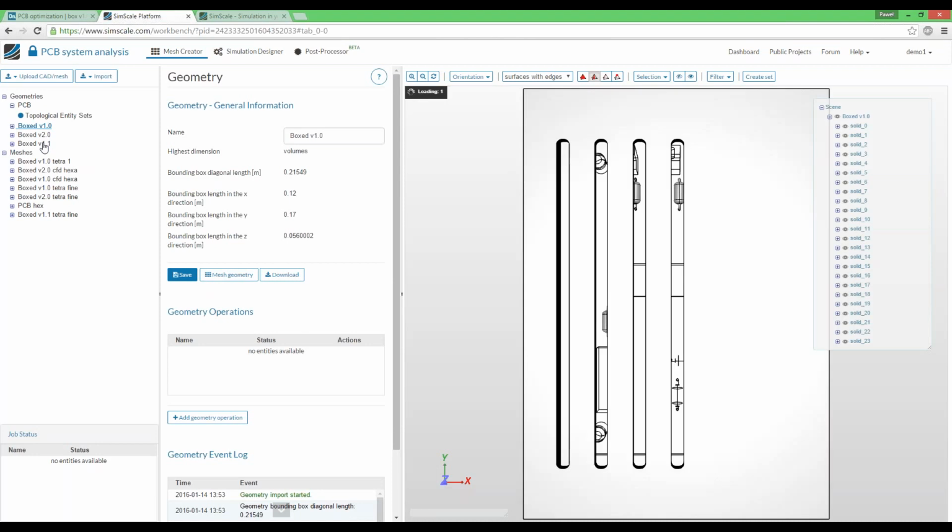There is a question, is the mid-surface meshing available? You mean a surface that is within the geometry itself? In general, you should provide a geometry or a solid element that is whole within itself. If you have surfaces inside, they will be considered as obstacles for the mesher itself. Or you can have the part made of several elements that later will be bonded with specific contacts.